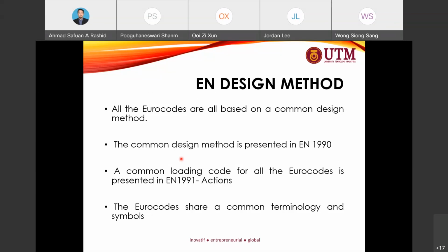We still use the theories, for example for shallow foundations we still follow Meyerhof and Terzaghi, and for deep foundations we still identify the friction and the end bearing. However, we just include some new symbols and new factors in getting the factor of safety of the problems.